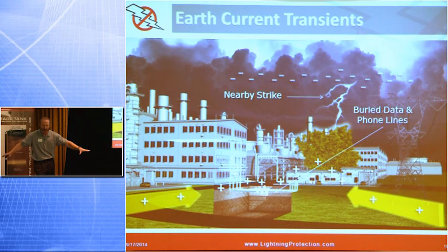So as that positive charge flows across the Earth's surface, it induces a voltage transient on those buried cables. And that voltage transient will go both directions, onto the field side instrument as well as the control room side. So we can have a scenario where we have an instantaneous failure of our field electronics, or maybe an I/O card at our DCS. That's the obvious one, anybody can figure that one out. I had a lightning strike, I heard the thunder, bam, I lost that instrument in the field. Pretty easy to say that was a lightning generated failure.